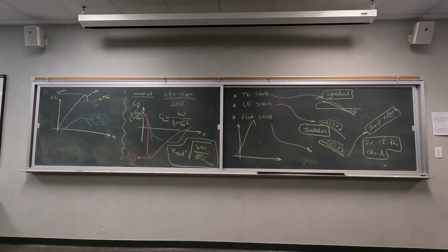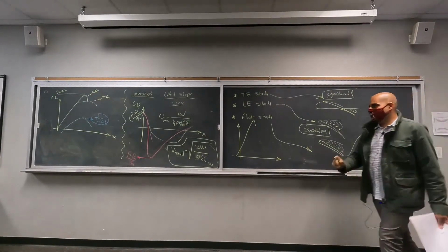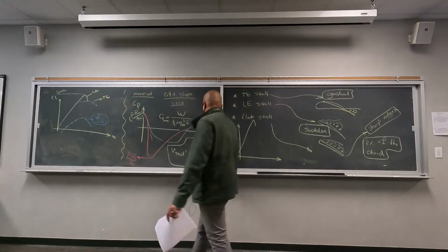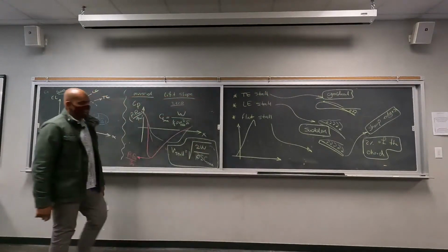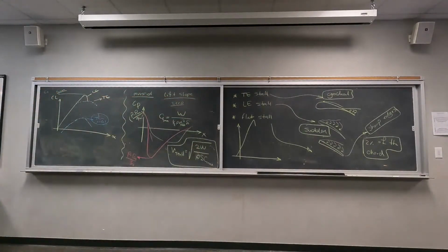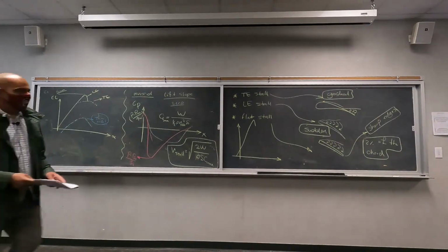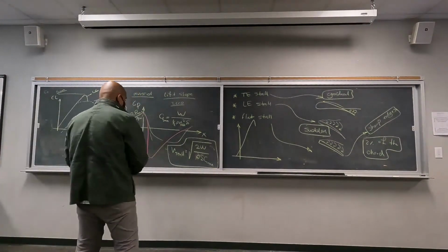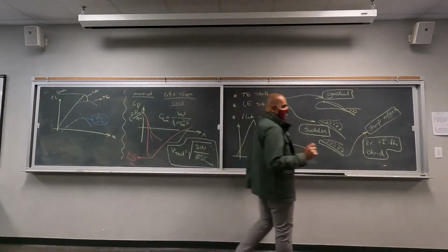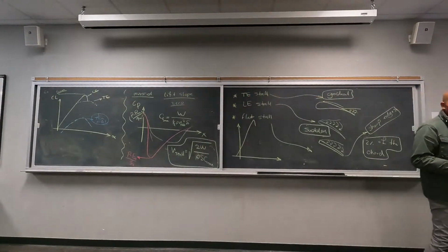I mean, you can see it from the equation. But if you keep the stalling speed also constant and let the weight change with a higher maximum lift coefficient for the same stalling speed, you can carry more load, right? You can have higher weight on your airplane. Okay, but the question is, how can we change that stalling point?